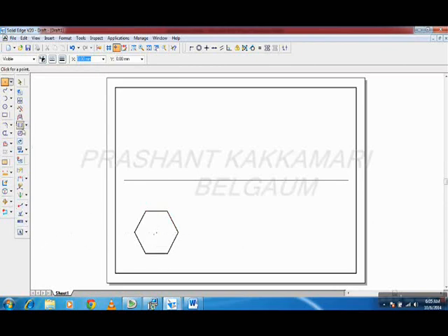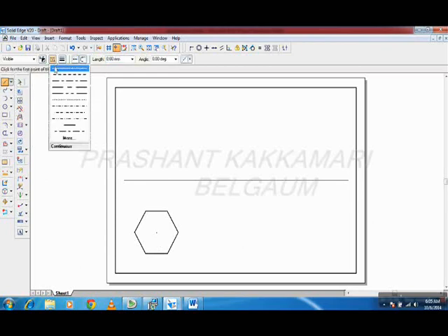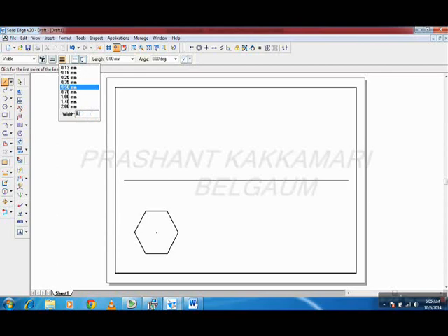Now go to projection lines. Take the projection lines, continuous, thickness 0.05, enter. Now see, this is one projection line. Then from here to here I will click one more projection line. You already know all these things.